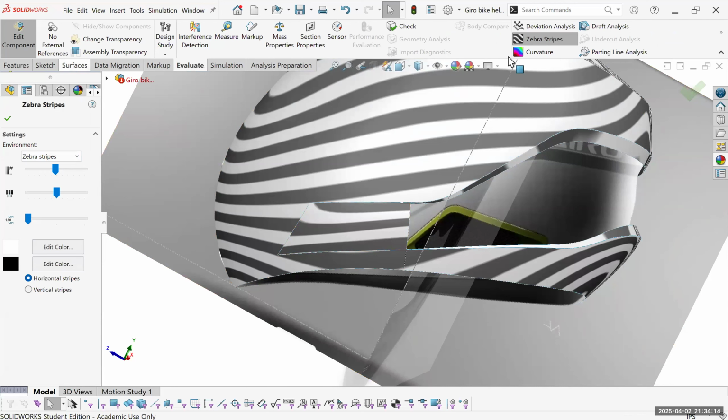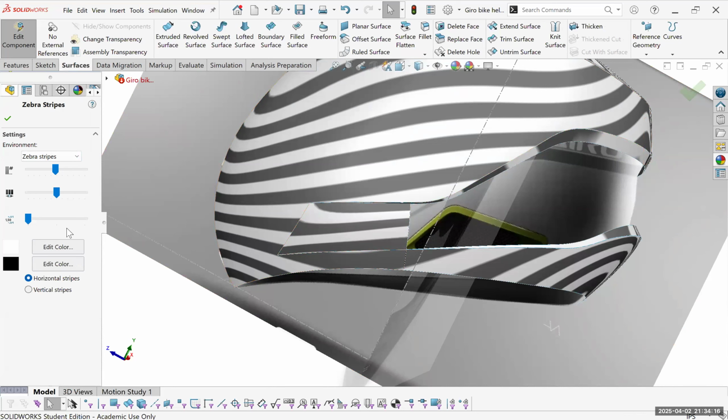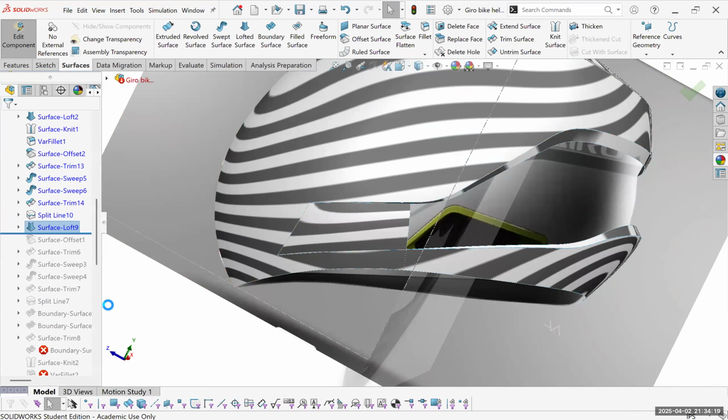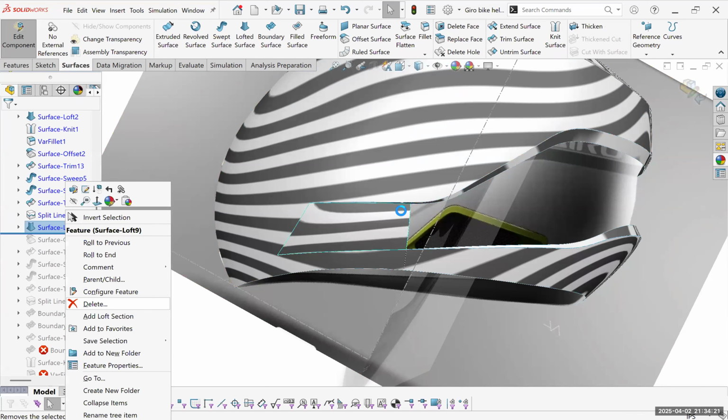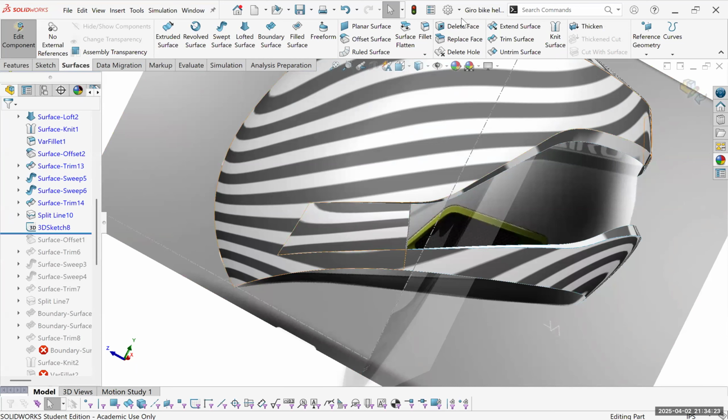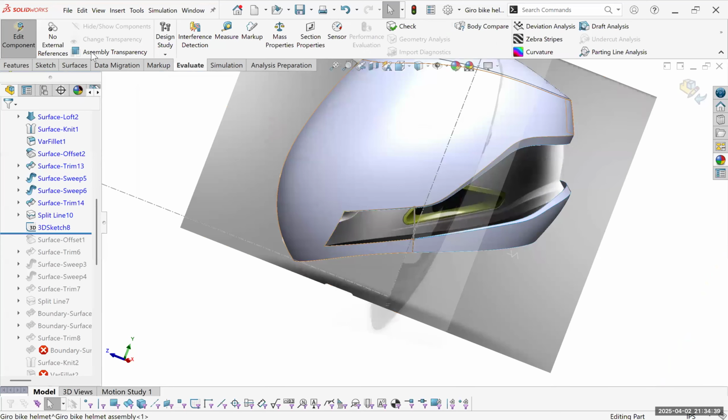Just gonna go back, and our last option would be the fill, but usually if you have a third, fourth edge, that would be the best one to do. Okay, I'm gonna go back to my boundary. It might be that this is a bit sharp, so we can always go back and kind of fix these points as well. For now, just gonna continue with our boundary surface.